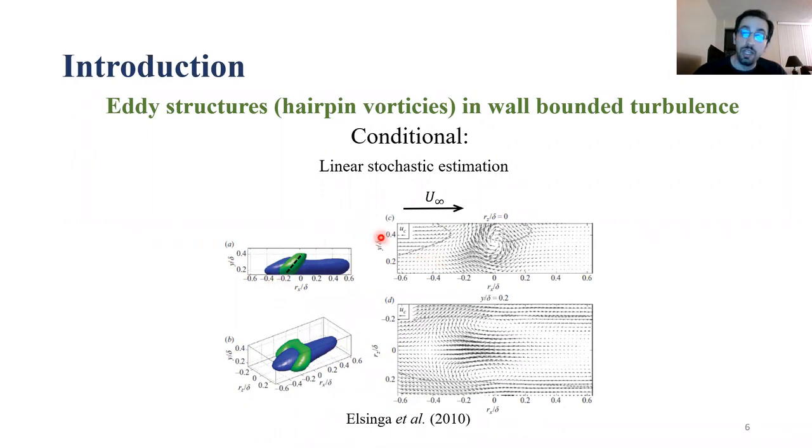Now we can again look at the cross surfaces. This is a wall-normal streamwise cross surface, and where we cross through the head of the eddy, we have this swirling flow caused by the head of the eddy, and these two swirling regions caused by the legs of the eddy when we look at the spanwise, streamwise plane. So these rotational regions are called the eddy signature.